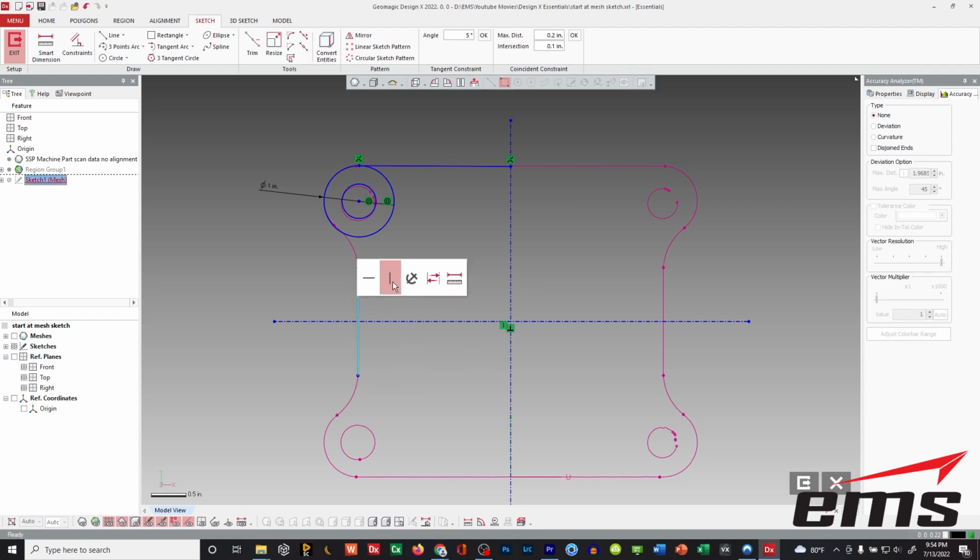Of course, I can right click it and say make it vertical, or I could draw a line, turn off fit polyline, drop my first point, and then just keep moving it till I get that constraint. So different ways to do the same thing. Okay, now let's go ahead and add our radius in.